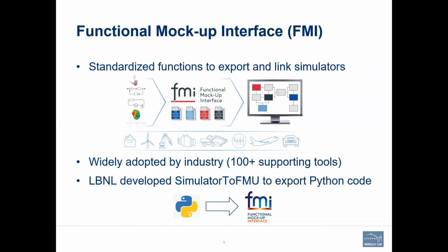Different models can be exported using this interface into an FMU, and then these FMUs can be linked together in various ways. There are two different ways of exporting or compiling such a model. The one mode would be the model exchange mode, where the derivatives of the model are exposed, but the solver is external to the model. So it needs a global orchestrator to execute the model. The advantage is that it can make use of variable time step solvers which roll back in time, since the integration happens outside of the model.